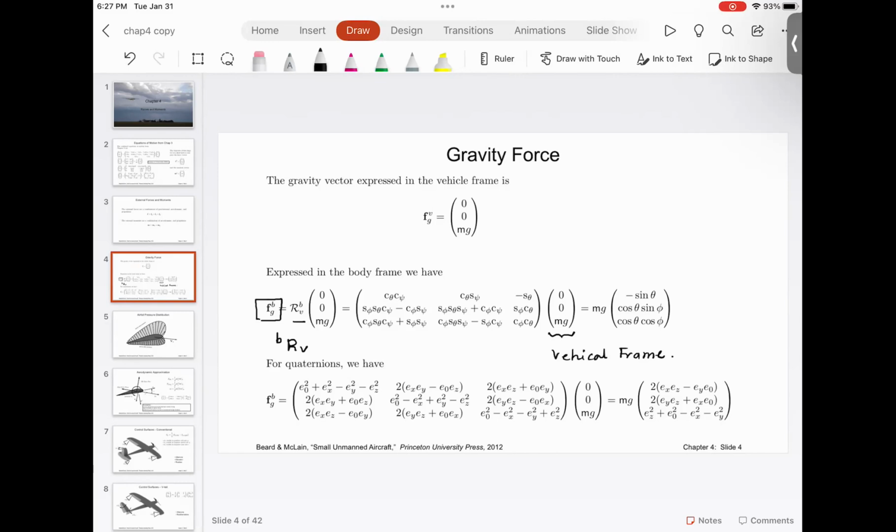So there is a concept which is called complementary filtering. So what is this complementary filter? What it does is it combines the roll angle computed by the gyro and the roll angle computed by the accelerometer and adds them together, adding some type of a weighing function. The idea here is, if you think about it, the accelerometer will give you a good estimate of pitch or roll when there is not a very significant motion.